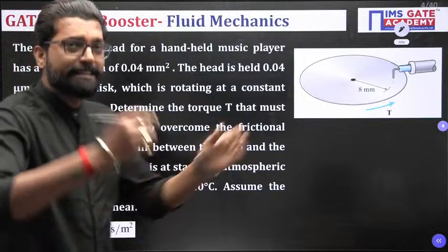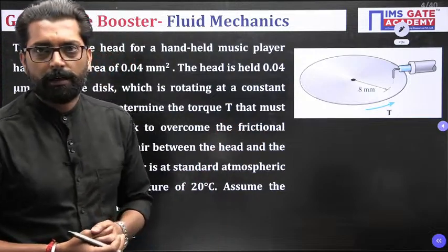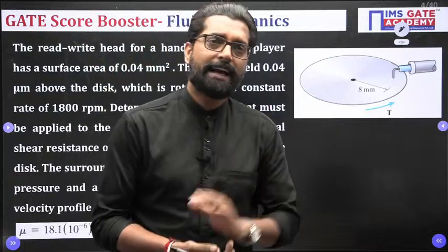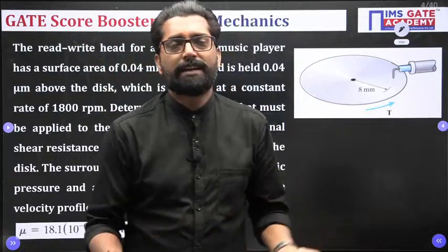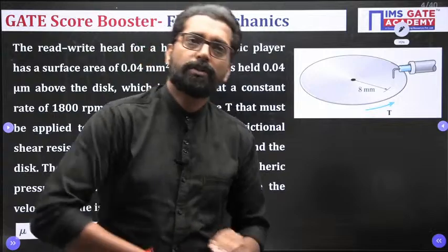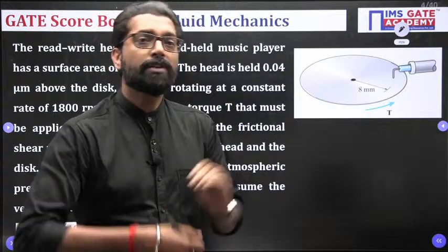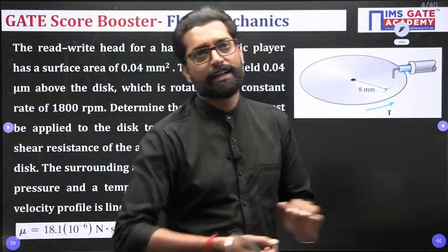See, for this type of problem related to viscosity, the steps are very fixed. First, you have to find the shear stress. Once you have the shear stress, you find the viscous force. Once you have the viscous force, you can easily find the torque.